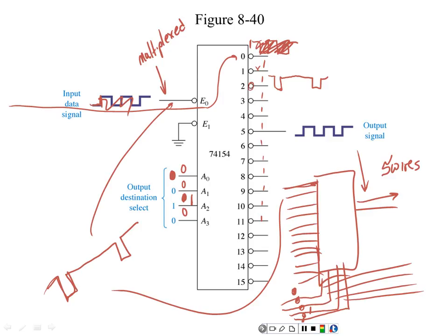But now you're sacrificing bandwidth, right? Because your wires only have a certain amount of bandwidth they can handle at any one time. So we could get to the point where the wire couldn't support it anymore. And wires have bandwidth because if we send a signal on a wire using electricity, we have to send a common. And we usually send them together. And what happens is these wires, if we run them close together, they set up this little thing called a capacitor.